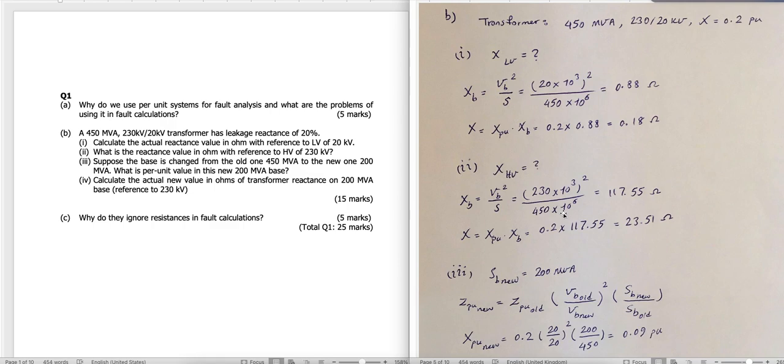But here, voltages are the same, so you don't have to put this part in the formula. You can just write the shortest version: V per unit new equals Z per unit old, S base new divided by S base old. So you always want to see it written before, if that makes sense? So you're saying if they're equal, you don't have to write.